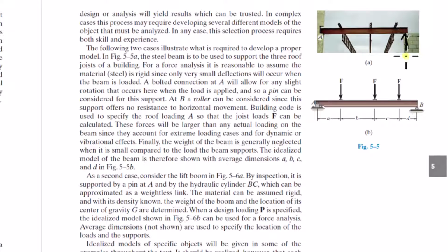It doesn't allow the beam to go up or down here. There is friction, but you don't consider friction for these enormous loads coming here. Friction is negligible, but that's okay. It's just preventing translation in a single direction, only certain directions relative to all the possible directions. Well, you just put that as a roller. There's no actual roller here, but you put a roller for the model.